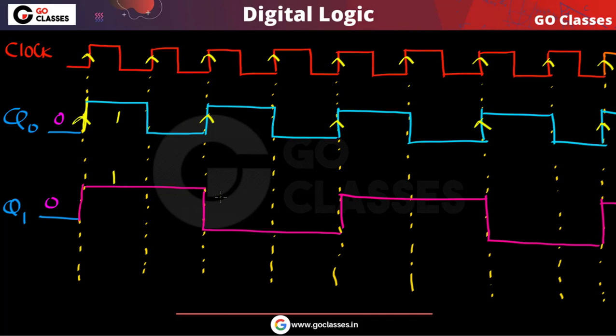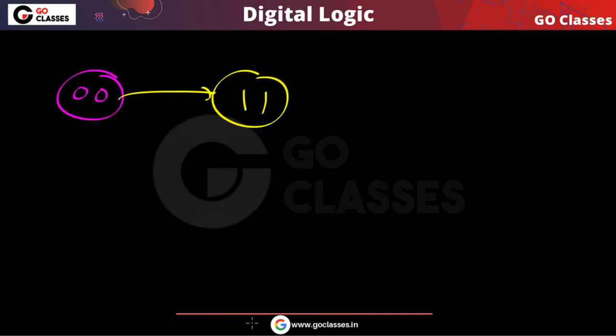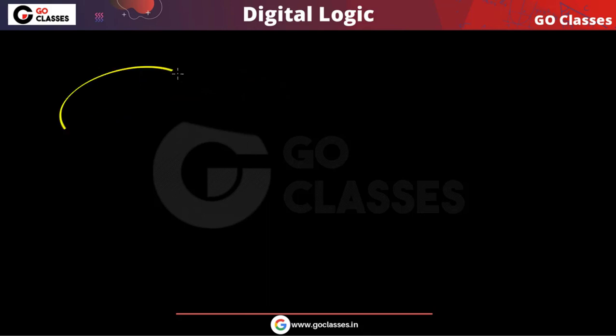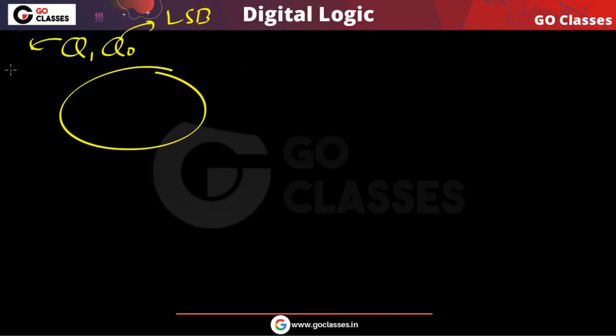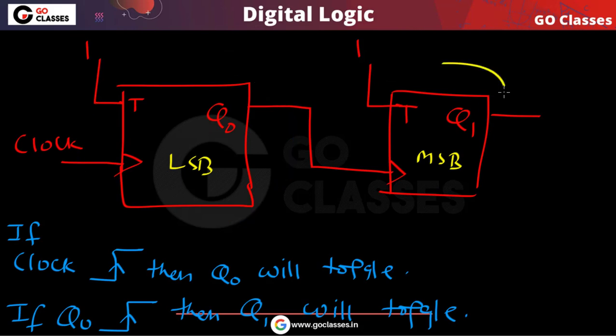And what is the next state? From 1 1, where are they going? You can very easily see that from this 1 1 they are going to 1 0, and then to 0 1. Let's assume that in this circuit Q0 is the LSB, the least significant bit, and Q1 is the MSB, the most significant bit. So I am writing Q1 Q0, because Q0 is LSB and Q1 is MSB.